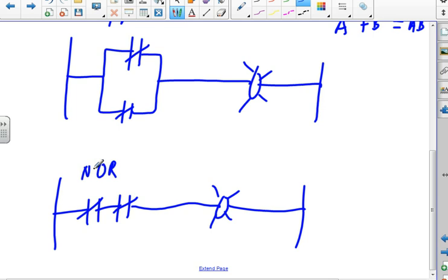So wire 1 goes from L1 to the high level switch. Wire 1, 2 goes from the L2 position to push button stop. 1, 3 is the wire that goes from start to stop. 1, 4 goes from start to the motor. 1, 5. So I would label them that way.